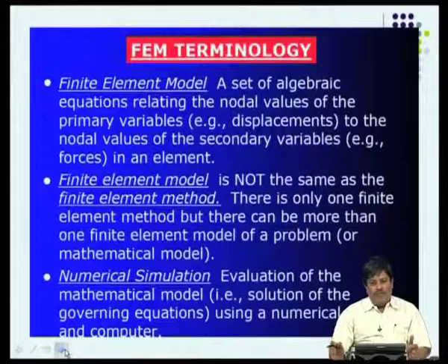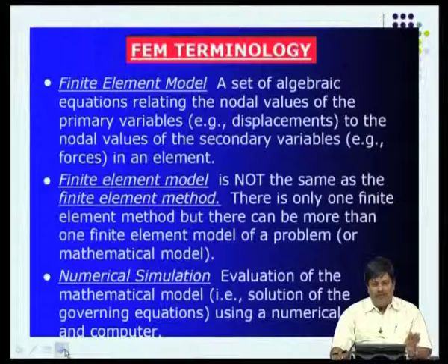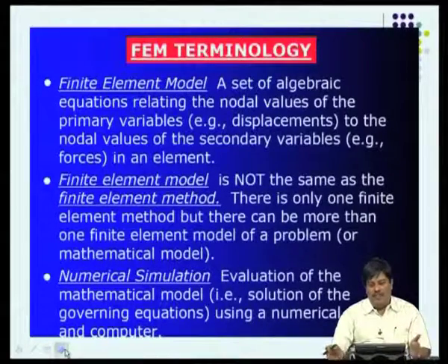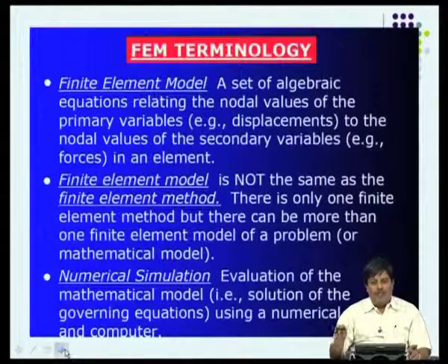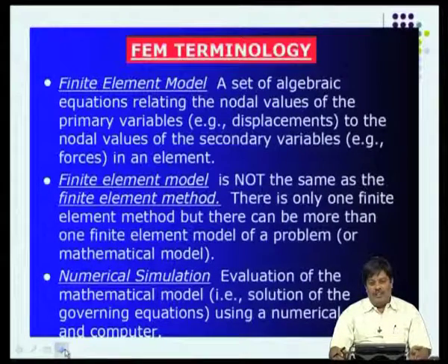So, what is a finite element model? A set of algebraic equations relating the nodal values of the primary variable. Here we have said displacement. If it is a heat transfer problem, it is temperature. If it is an electromagnetics problem, it is either the electric field or the magnetic field or both. So, a set of algebraic equations relating the nodal values of the primary variables to the nodal values of the secondary variable. The secondary variable can be forces or the heat flux or the magnetic flux, etc. It depends upon the problem.